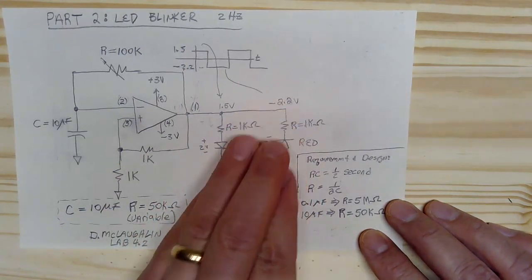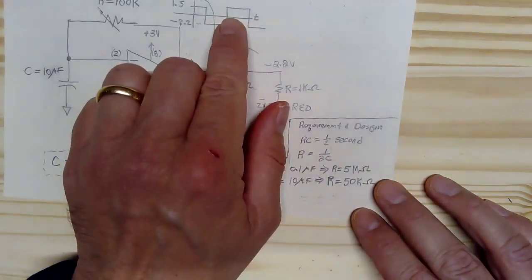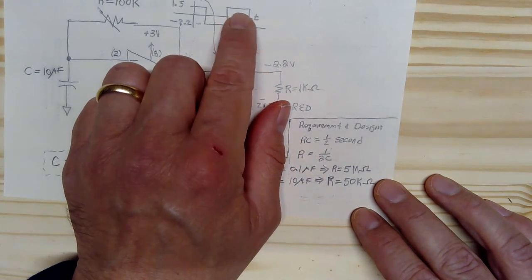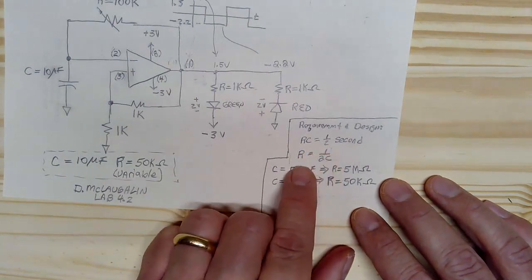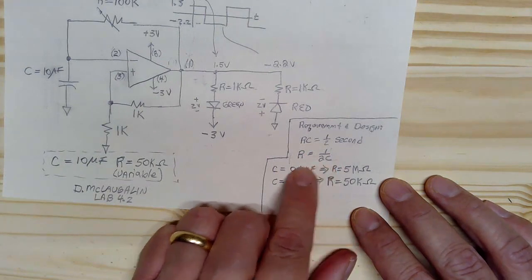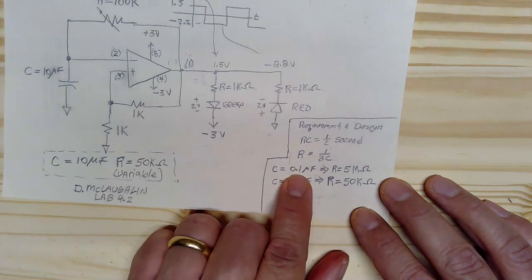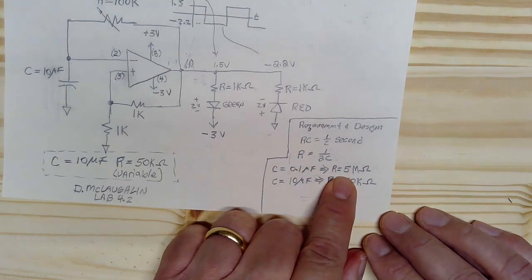Before we get into that, let's just look at how to choose R and C. We want the duration of each of these pulses to be RC seconds long, right? We want each of those to be half a second. So we want RC to be 1/2 second, or R is 1 over twice the capacitance. We have 2 capacitors, a small one and a big one in our kits. If we use the small one, 0.1 microfarad, then we'd need to use an enormous value of resistor, 5 megohms.